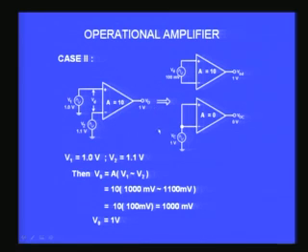That means this type of amplifier is not at all worried about the signals which are common to both the inputs, whether it is 0 and 100 millivolt, or whether it is 1 volt and 1.1, or it is 5 volts and 5.1, whatever, the output voltage is 1 volt, which is just the difference in voltage multiplied by the gain. 100 multiplied by 10 is 1 volt, and that is constant irrespective of what is the common voltage that I have at the two inputs.